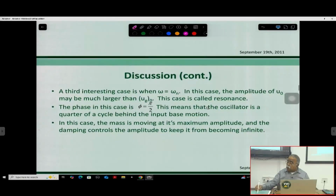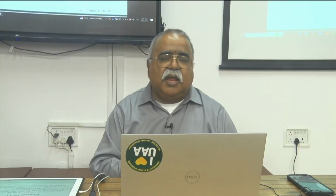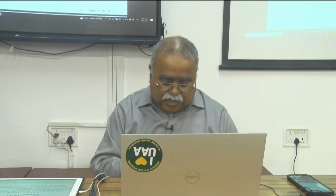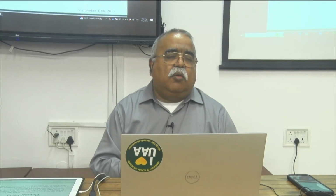And if omega is equal to omega n, so that means the ground frequency is the same as the building frequency, then what will happen? Then the building will be set into resonance, right? So the building oscillations will be much higher, and it will be a tremendously vibrating body, which as an engineer or designer, we all want to avoid.